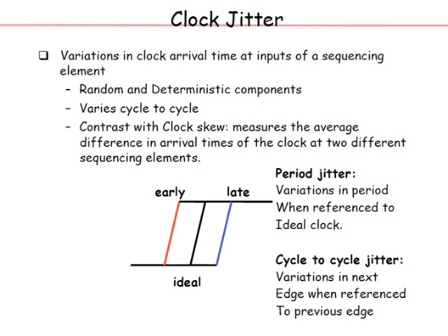Okay, period jitter is where I have an ideal clock and I am comparing the period of my clock to that ideal clock. Now for digital timing closure and so on, the cycle to cycle is important. Why? Because my edge launches the signal, the next edge in the cycle captures it, which launches for the next and so on.